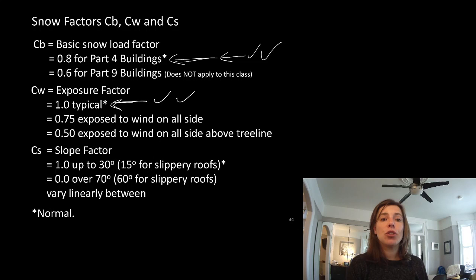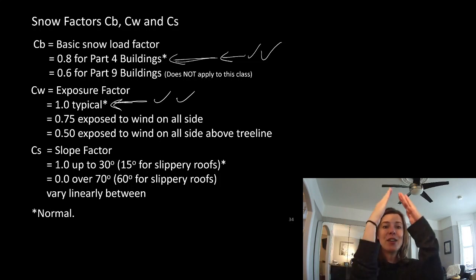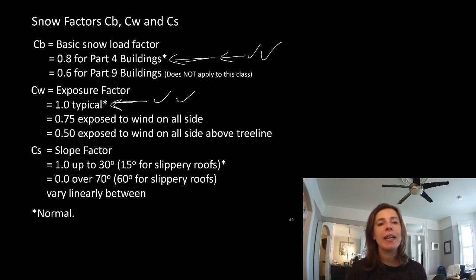Now, in Toronto, you don't see a lot of really steep pitched roofs. A lot of architects will be like, this is going to save the world. We're going to steeply pitch our roof and get rid of all of the snow that's on it. Well, in actuality, the snow loads in southern Ontario aren't that high. We don't benefit that much from it because we still have all the weight of the material. Now you've got an increased zone for wind blowing on it. It ends up being more materials, more zone to heat. So economically, it is not